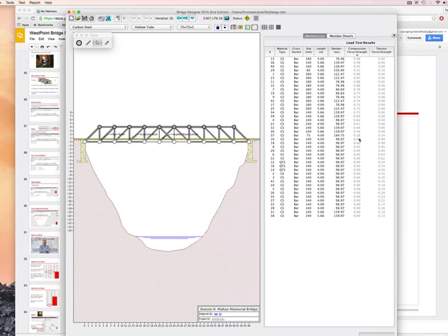All right, let me go back and look at this and go, well, I can't do it with a hollow tube necessarily. I have to make it a bigger hollow tube. So it's always these constant trade-offs and playing with it. And all right, that's a solid bar at that. Maybe if I made it 90 by 90, that went up a little, but now I make it a hollow tube. And still draw the price down. Let's see what that does.